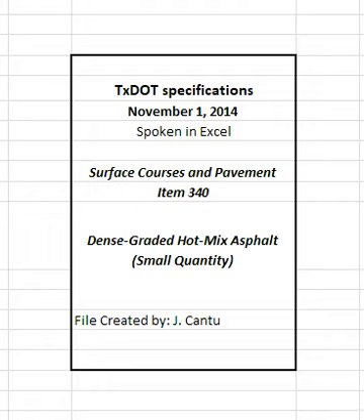When WMA is required, the maximum placement or target discharge temperature for WMA will be set at a value below 275 degrees Fahrenheit. Department-approved WMA additives or processes may be used to facilitate mixing and compaction of HMA produced at target discharge temperatures above 275 degrees Fahrenheit, however, such mixtures will not be defined as WMA.